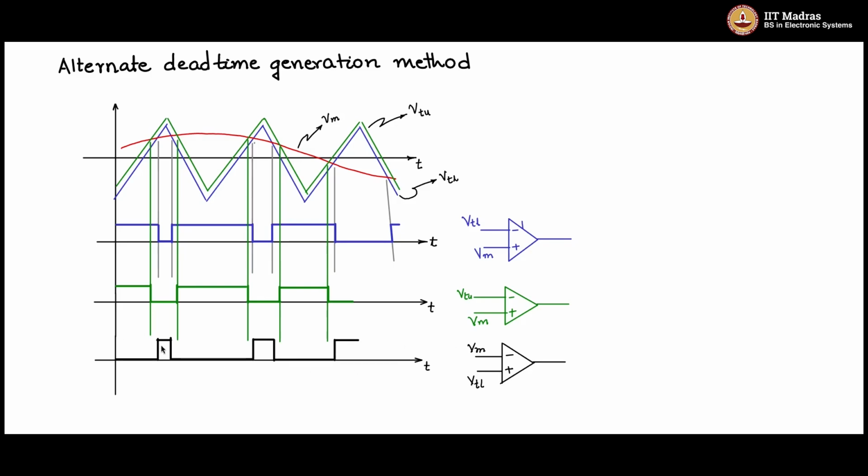So you see that this and this waveform together form our requirement. So let me complete this. So you don't forget the VCC and VEE, plus and minus 15. And you have to have a clamper, Schottky clamper like we discussed before, so that this becomes just a unipolar waveform like this.